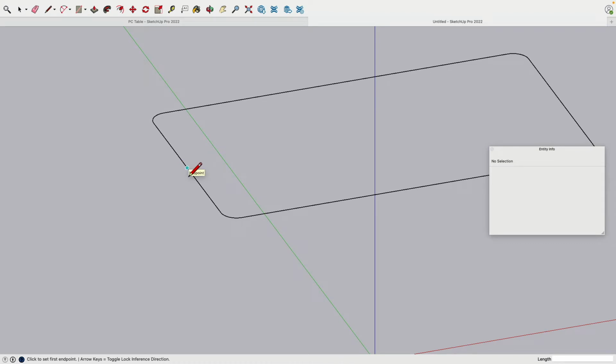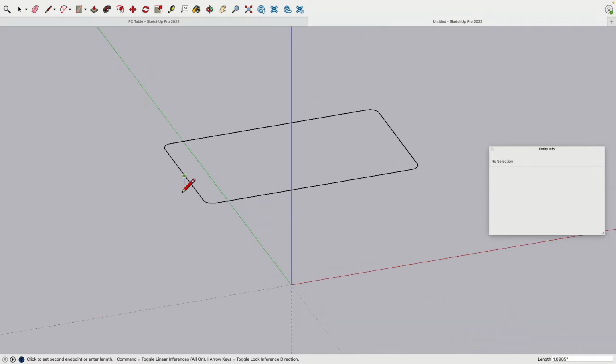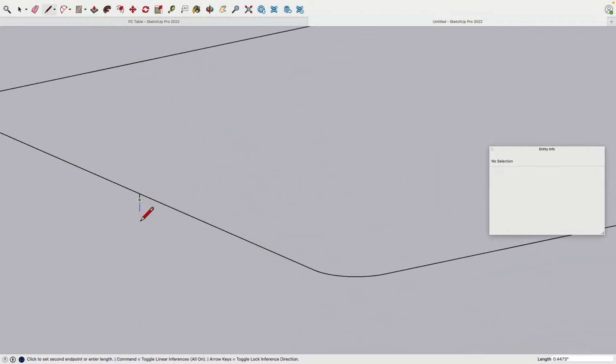On any edge, this one or here, I need to find where the midpoint is. And then I draw a line down, 0.25, along the z-axis. Now that's important. And then another segment, 0.5 of an inch. Cool. I have two segments, important to keep in mind. With nothing selected, I can go to move, select this endpoint along the x-axis.